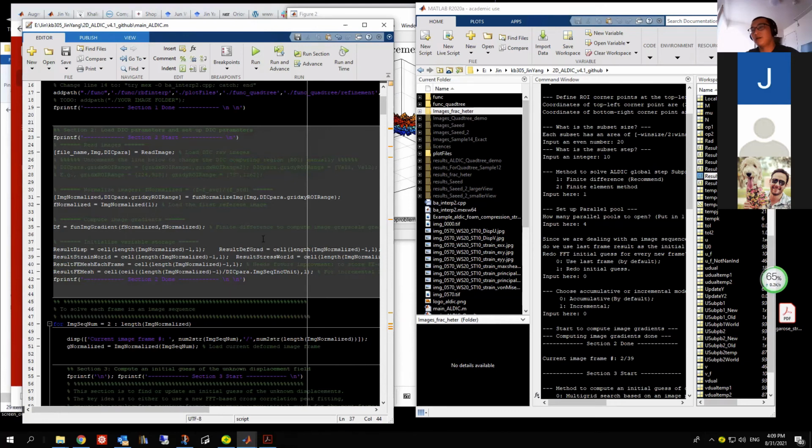If the deformation is super large, many specimen areas will be out of the view. If you compare with the first image, there is nothing to compare, so it's also not meaningful to compare them. So the accuracy is low because you rely on lots of extrapolation. Extrapolation always has less accuracy compared to interpolation.